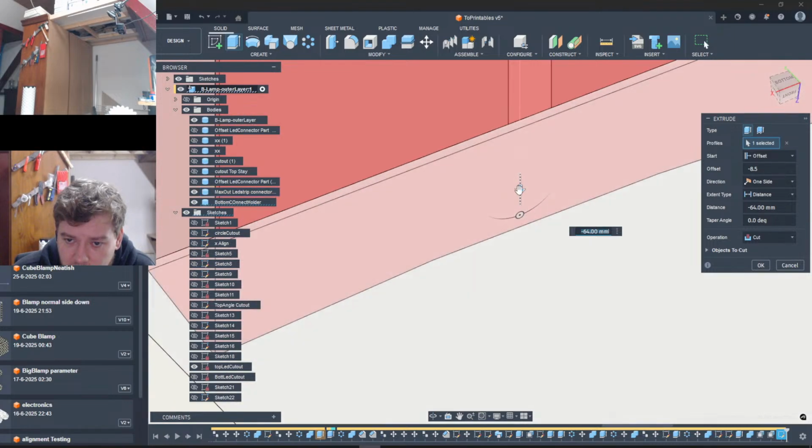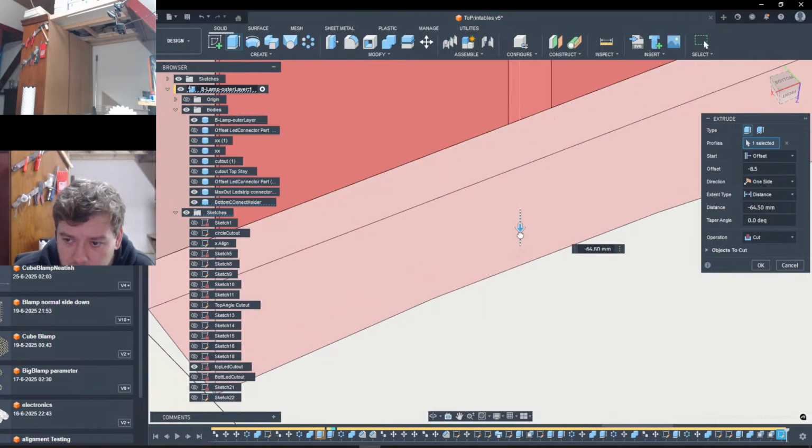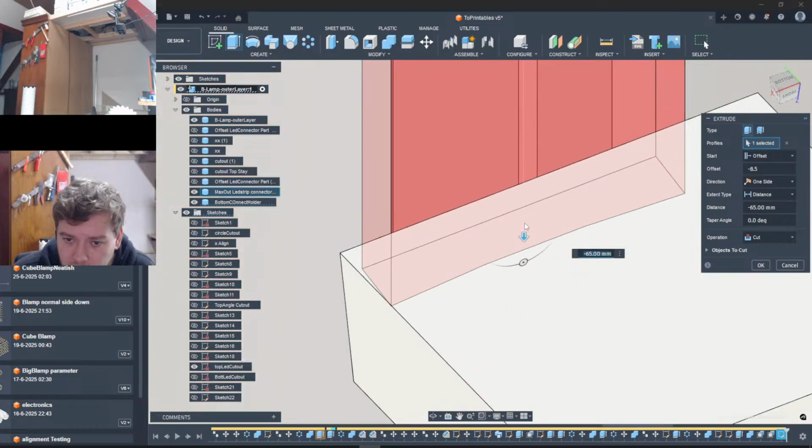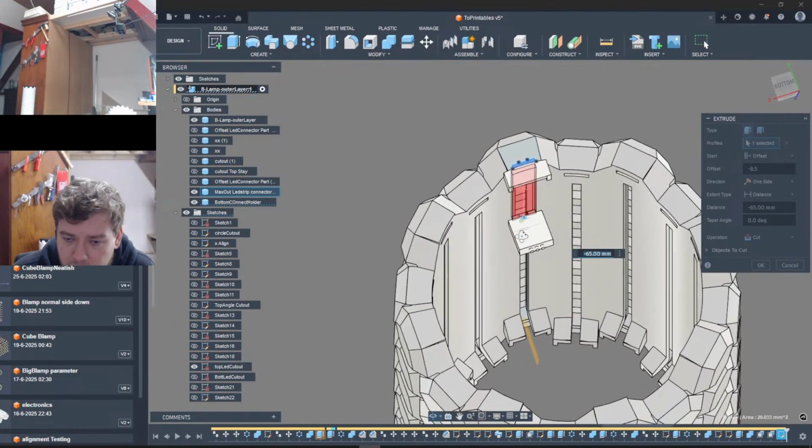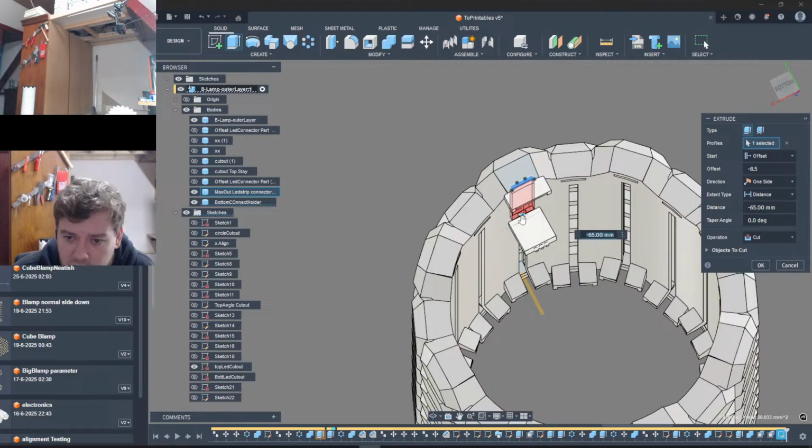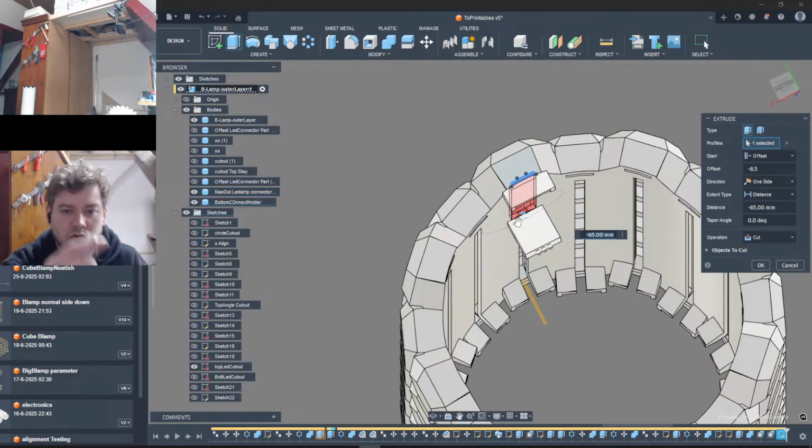We said 65, so 65. That's the space, and it's not gonna get loose because the connector clip itself is still bigger. So it doesn't get loose. The LED strip itself can get loose at the moment until you get that small connector pin in, and then it lines up. So then that part has a lot more breathing room, saves plastic.